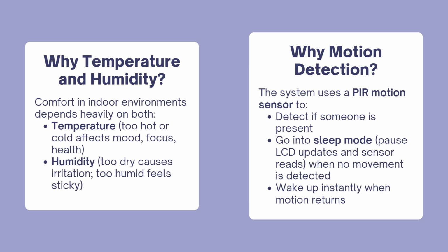So why motion detection? The system uses a PIR motion sensor to detect if someone is there or not. If there is no one there, it will go to sleep mode, aka pause the LCD update and sensor reads, and it will wake up when motion returns. Next one.